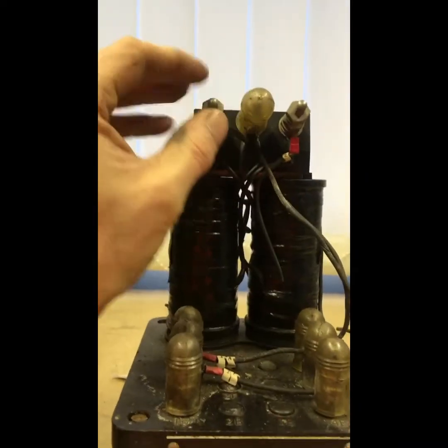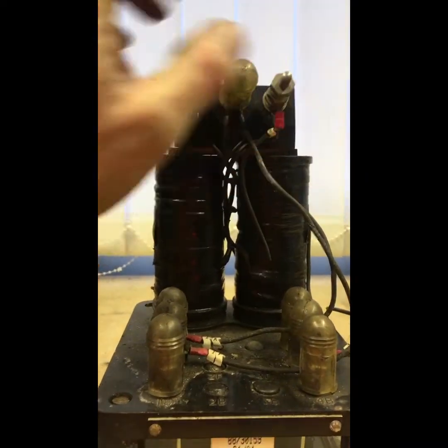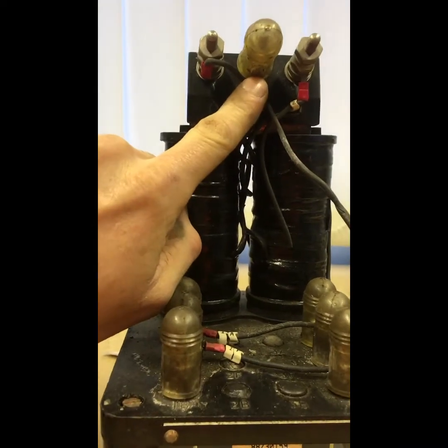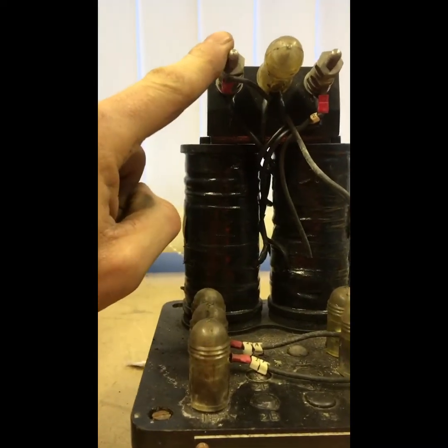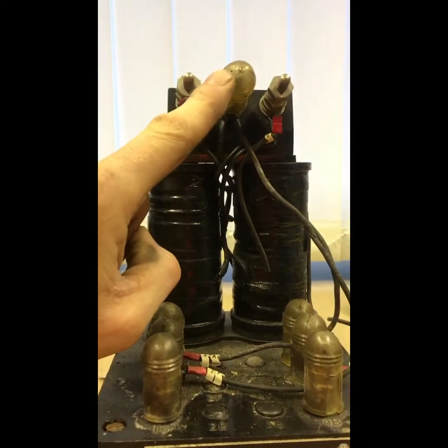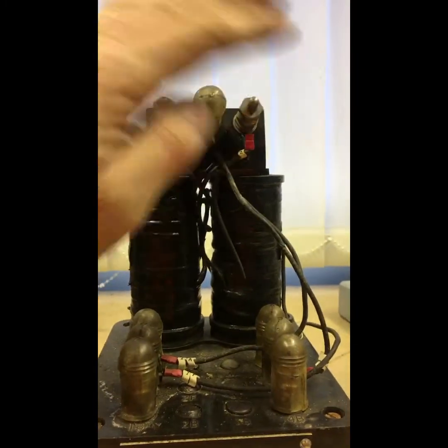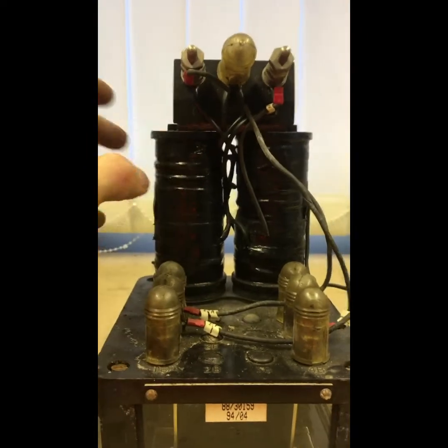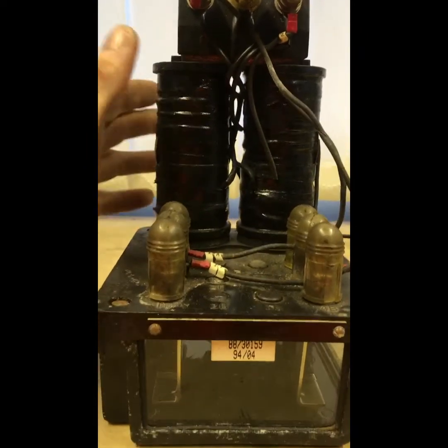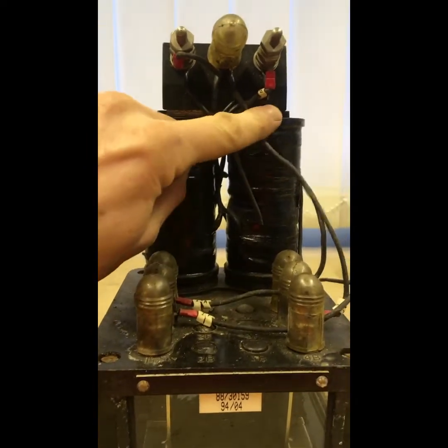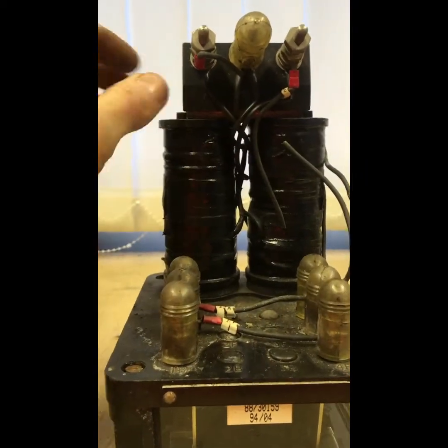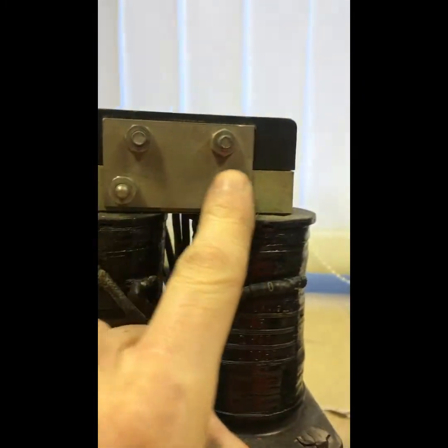So you can appreciate, coils R1 and R2, centre stud terminal, so it comes in, goes through the coil to the centre stud, goes to the other coil, back out, and off you go. So your positive and negative to your track relays, to your track links, and also a central coupling bar through to hold the magnetism through, which is what this top affair is for. You see it on this one. So there's your central coupling bar.